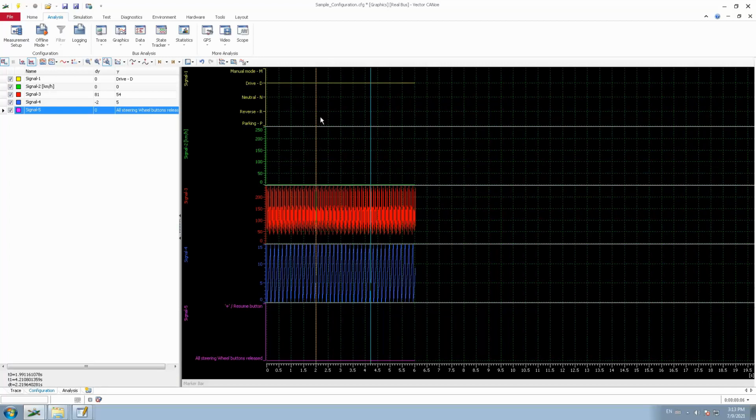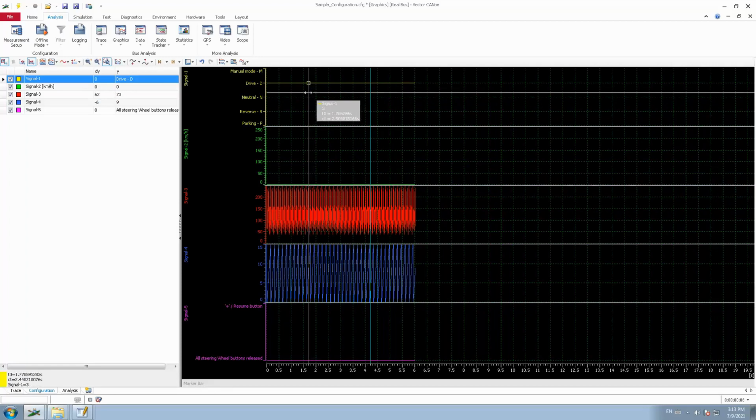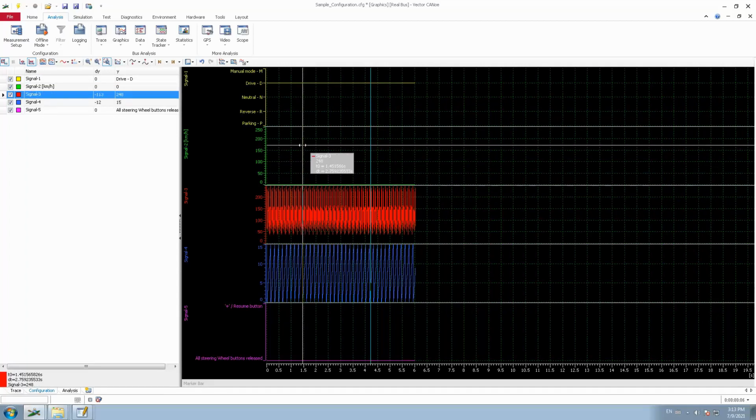Some tips and tricks: you have to select the signal first, and then you can start to move the cursor. When you have selected the signal, you will find a square highlighted point which shows which particular point you are going to set as the start point. For instance, if my start point is not in signal 1 but in signal 3, then I can go over here.